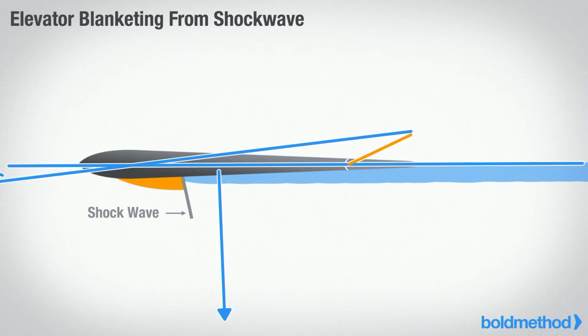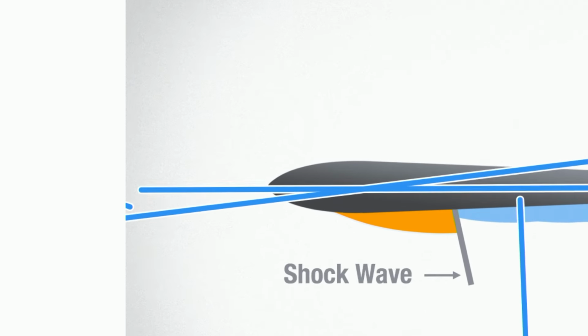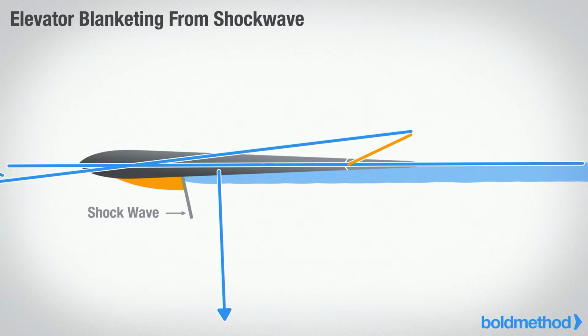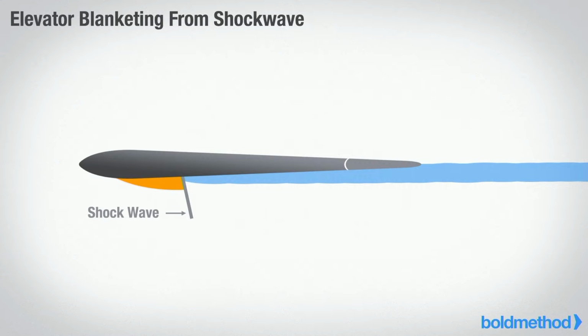And the reason we do that is because that essentially creates, you can kind of see it at the very end of the video, a positive angle of attack, right? And that positive angle of attack would increase the magnitude of our lift. Okay, so by pulling back on my yoke in my 737, what am I doing? I'm increasing the tail down force. I'm increasing the tail down lift on my elevator. As I increase that lift, I'm increasing camber, I'm getting a bigger pressure difference between low and high. When we think about a wing, low's on top, high's on the bottom, but when we think about a horizontal stabilizer, the low is on the bottom and the high is on the top.